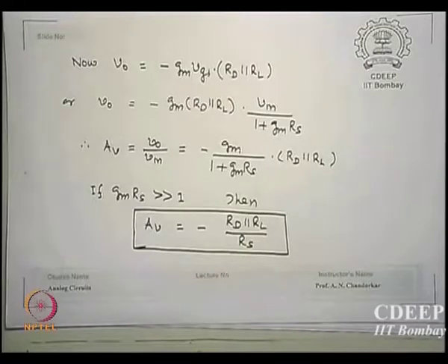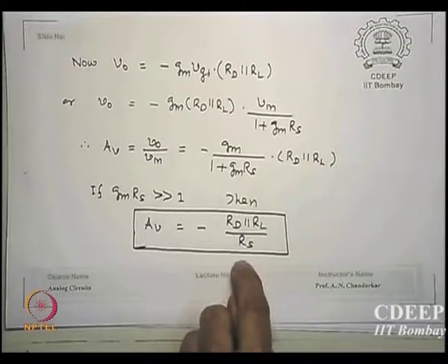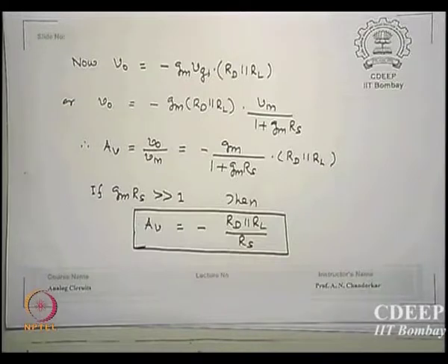Okay. Why is it temperature independent? Because even though these are temperature dependent terms, R has a positive temperature coefficient. But since they are, assuming, the same material, carbon resistor, the temperature coefficient of R in the numerator and denominator may almost be similar, and therefore they are independent of temperature. Is that correct? Is that clear? So what is the advantage I got?